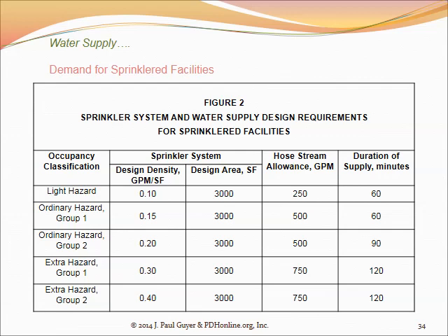And so sometimes when you're driving around in an industrial area, you'll see a warehouse-like building with a big tank outside, and that probably has fire protection water in it. So if the local utility can't provide the quantity of water that you need to protect your building, then you're going to have to store water on site.